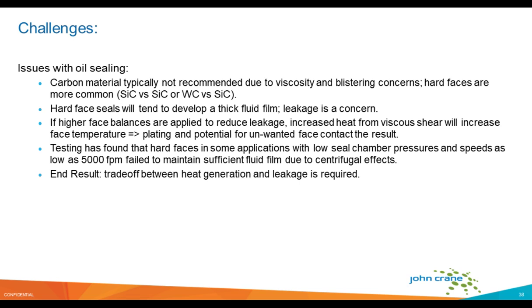When we're talking about an oil sealing application such as this, typically the viscosity is too high for carbon, even an antimony filled carbon, so we run into the possibility of blistering and causing damage to the carbon. And so then we have to look at alternative materials, which would be typical hard faces like silicon carbide versus silicon carbide, or tungsten carbide versus silicon carbide.